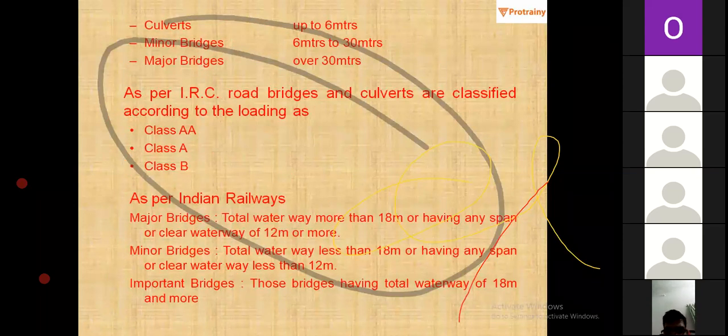When it comes to loading, there are two types of loading when we are talking about a bridge. The loading category we have covered in this session is whatever load is coming due to the occupancy of the bridge, whatever type of vehicle is going to pass over your bridge deck. But when it comes to dead load, like the load of a deck coming over to the columns and the load of the columns and deck coming over to the foundation, definitely we are going to analyze those loads as well.